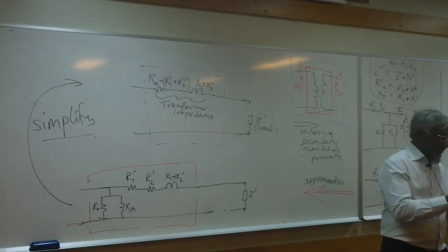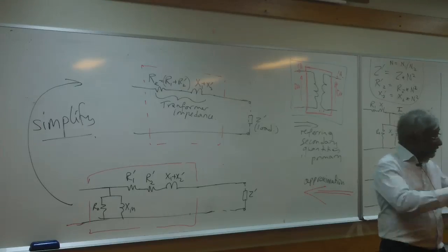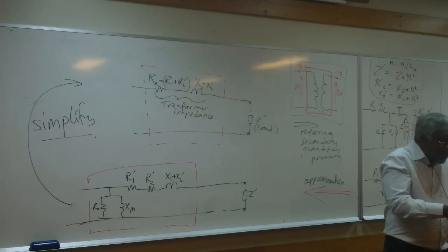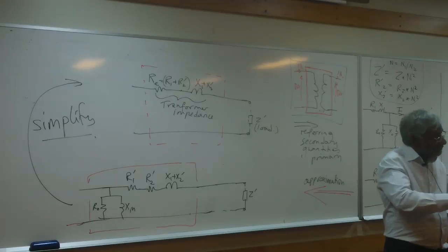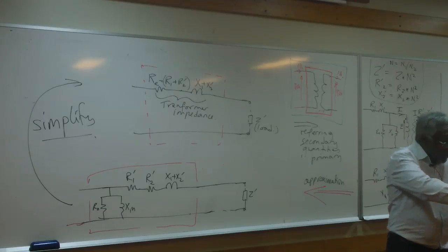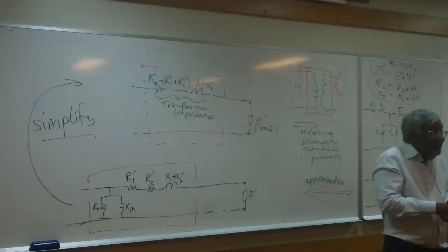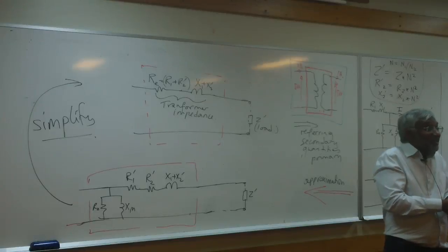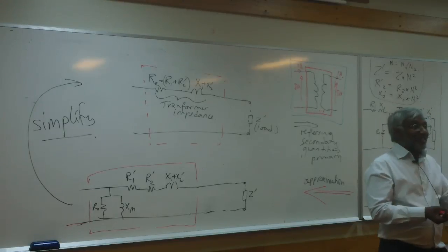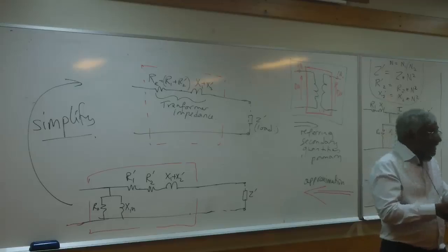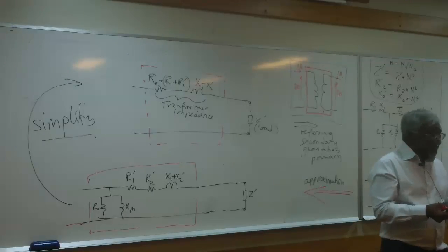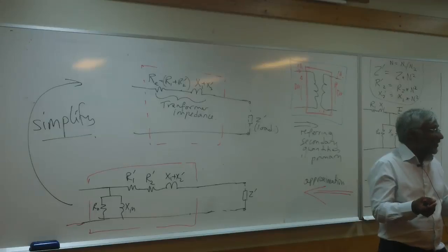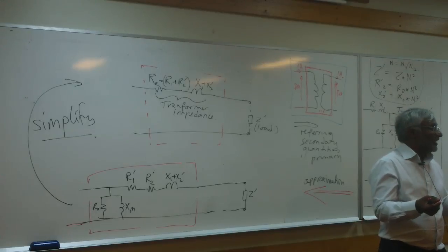And you have to wind it toroidal. So you use a toroidal core with your turns uniformly distributed around this core. You can do this at home on paper. Draw that on paper and try to draw the leakage flux. You can't do it. Where's the leakage going? You find it can't go anywhere.